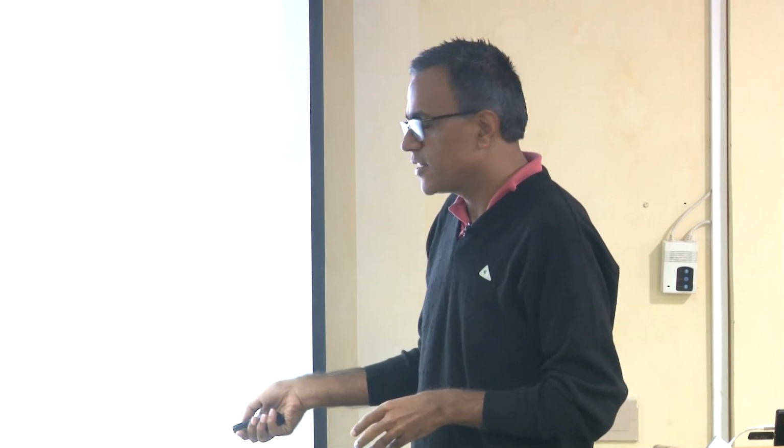If you want to understand more about it, you have to read this paper, wherein you make these channels, which are not orthogonal in frequency domain, orthogonal in time domain using the cyclically shifted version, estimate them there, then bring them back to frequency domain. That's the key idea.